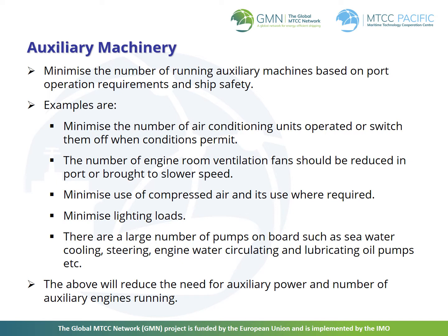The main aim of the plan will be to save energy through switching off the unnecessary machinery. As examples, the following may be undertaken. Minimize the number of aircon units operated or switch them off when conditions permit. The number of engine room ventilation fans should be reduced in port or adjusted to slower speed.